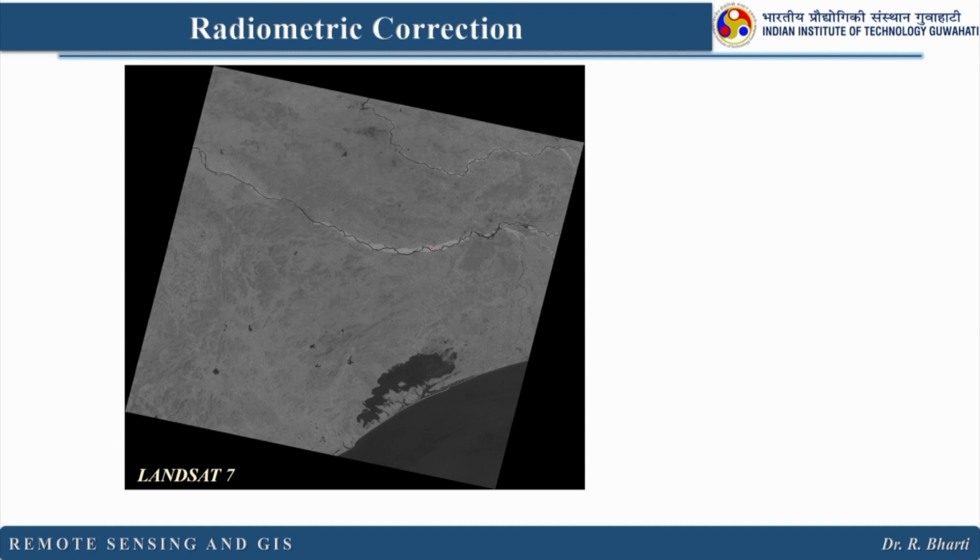If you see from outside, from a zoomed-out image, you won't find any problem with this. I cannot say that it is having a bad pixel. So what you have to do is run an algorithm which flags or identifies the values 0 and 255.